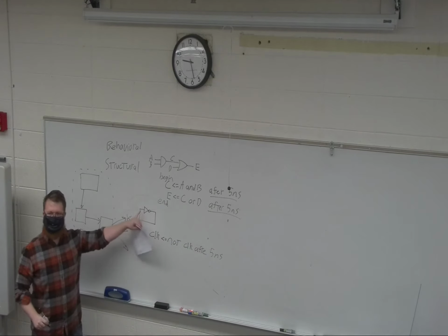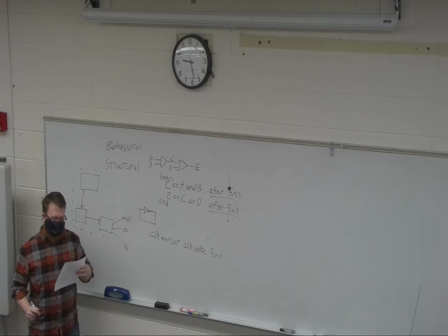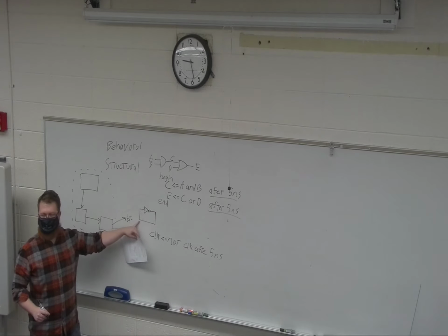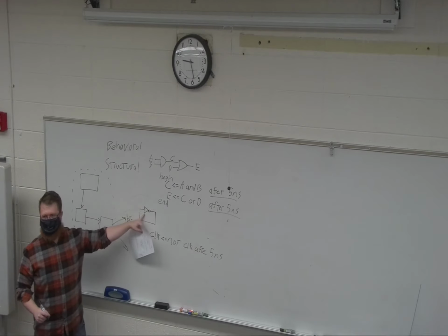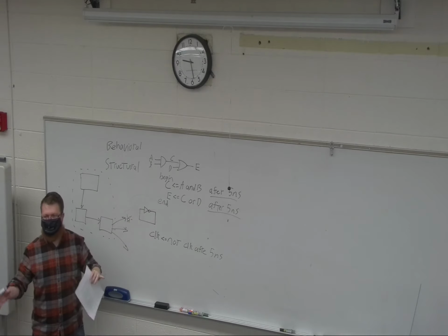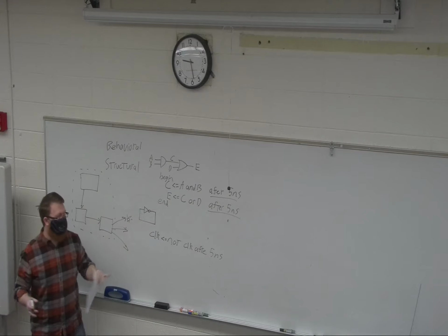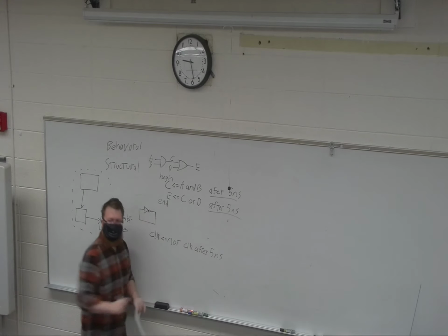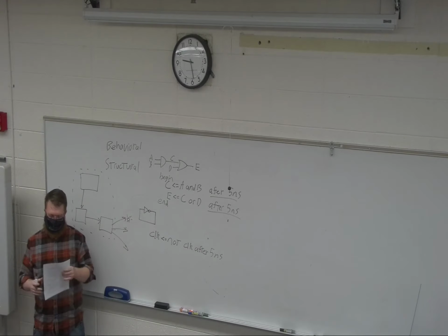That's basically all that is. It will implement that if I synthesize it, but it's not going to actually have a 5 nanosecond delay. It can't make that gate have exactly a 5 nanosecond delay. There's going to be an issue, which is why the after is not synthesizable.